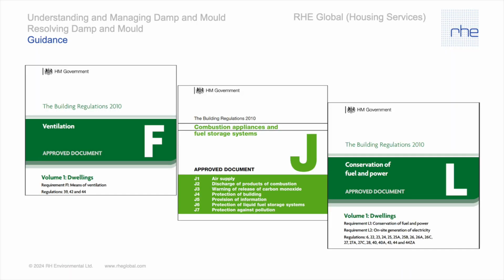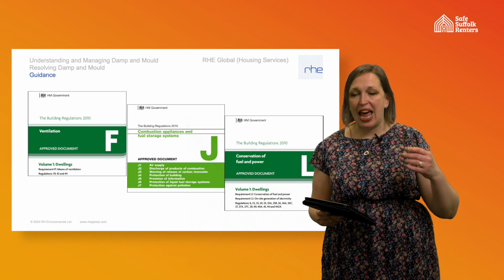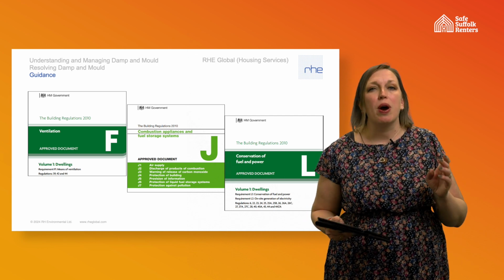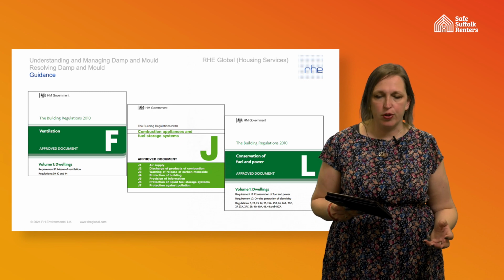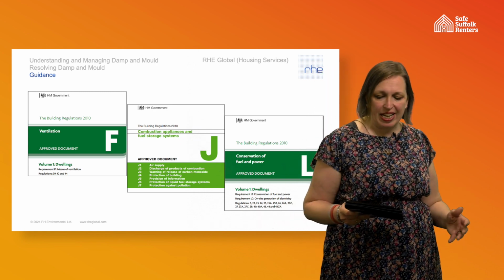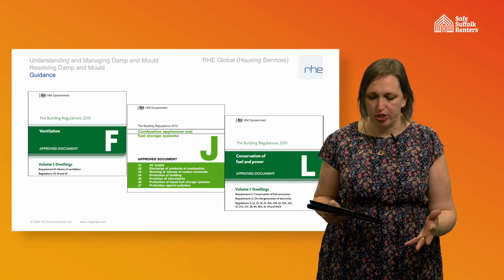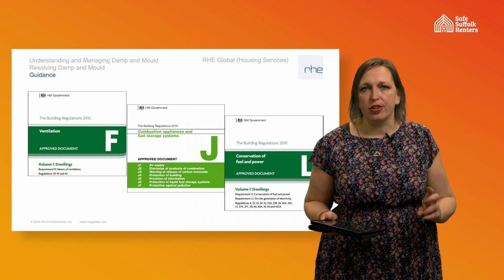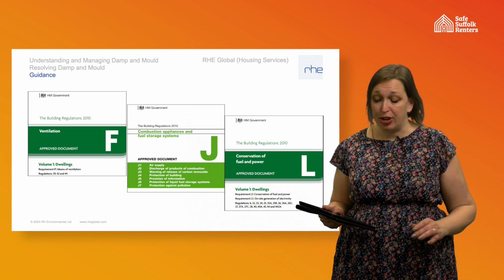And in terms of our building regulations, very similarly to what I said about the British Standard just there, when we look at parts F and L of the building regulations, there is also a different approach for traditional buildings in that ventilation and energy efficiency improvements should only be made to vapour permeable construction where it won't cause deterioration of the fabric of the dwelling. So really important to recognise though that doesn't mean don't do anything. What it means is that the measures should be appropriate to the dwelling, and it might mean that they don't meet the ideal prescribed standards, but we still need to make as much improvement as we can.